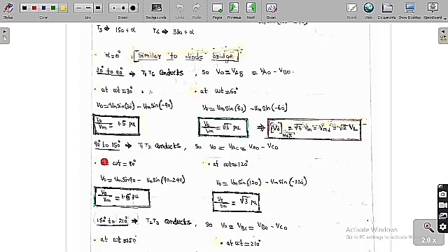Now I want to analyze from 90 degree to 150 degree. I want to analyze what the waveform is from 90 degree to 150 degree for the same alpha equal to 0. From 90 degree to 150 degree, T1 and T2 are going to conduct. Therefore, if T1 and T2 conduct, the output voltage is equal to VAC, which is VA0 minus VC0.